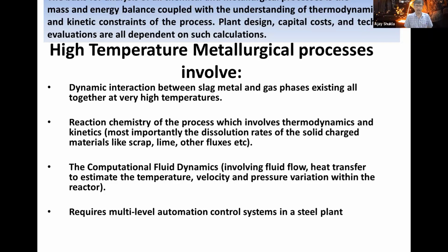If you look at any high temperature process in general, be it in steel making, iron making, or even in non-ferrous extraction, we deal with the dynamic interaction occurring at very high temperature between the slag, metal, and gas phases altogether. There is also a lot of interaction with the dissolution of solids and other phenomena. We need to understand the reaction chemistry of the process, which involves thermodynamics, kinetics, and dissolution rates of solid charged material like scrap, fluxes, etc.